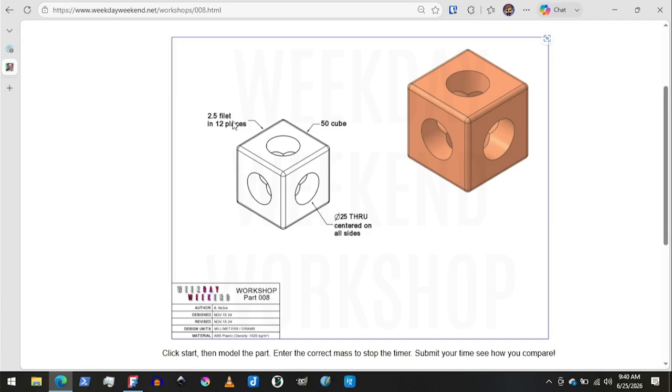I don't necessarily have to do it that way. Over here, I'll do another one. So I can just click and drag, and then pressing D, I can go back and set my dimensions afterward. So if you prefer to just get the shape and then go back and put in precise measurements, you can. It's up to you. There's a lot of different workflows you can use, so don't feel like you have to do it one way. So my drawing is done.